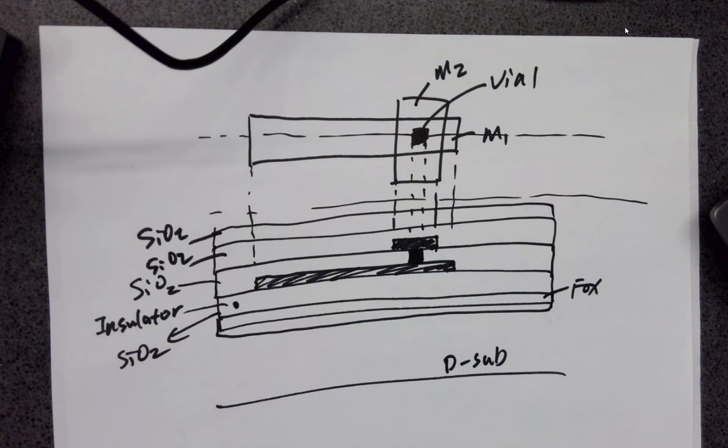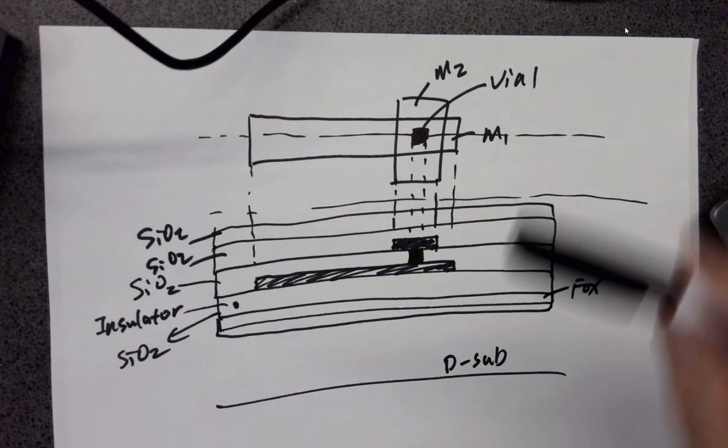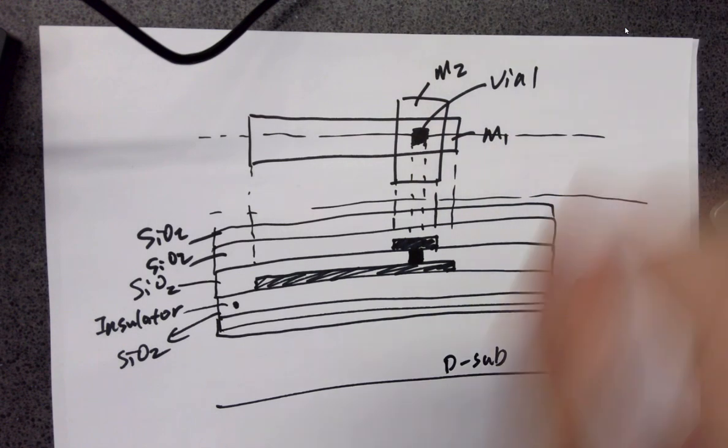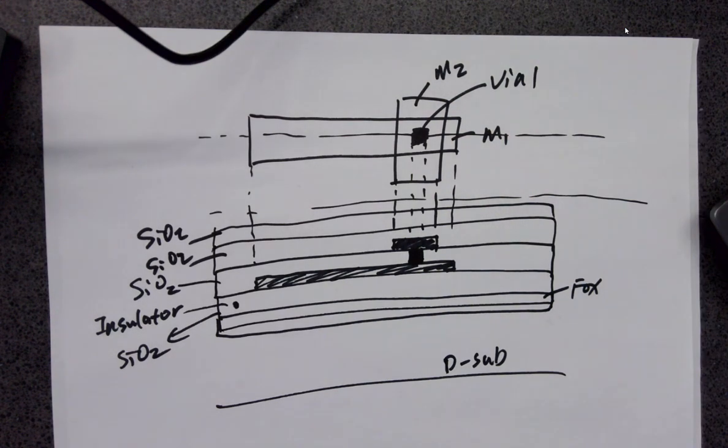So more layers will be more helpful to have more highly integrated circuits because you are able to route your wires in a relatively more concentrated area. Okay, because whenever you cannot route it through all these wires, you can always dig a hole and route it on the top, right? So more metal layers will be more helpful for layout.